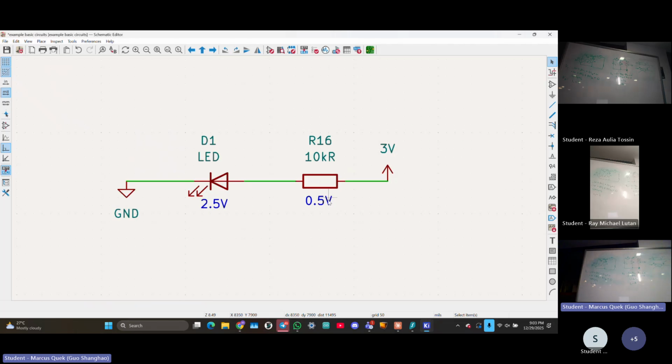So this is a breadboard, which is what amateurs use to design basic circuits. At the end of the course, you will design PCBs, which is what adults use. All of these rods are where sockets are connected to each other. All the sockets in one row are connected, but rows are not connected to each other.